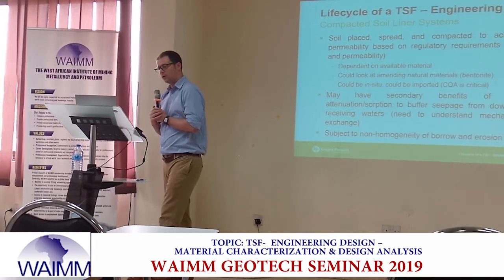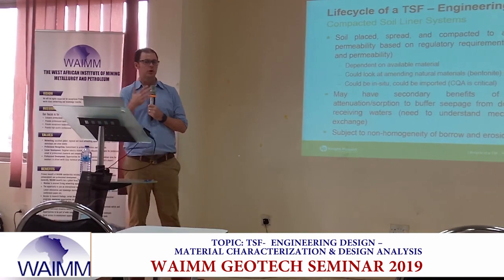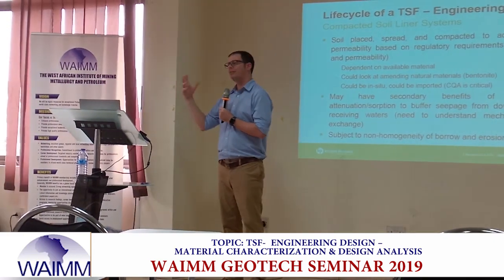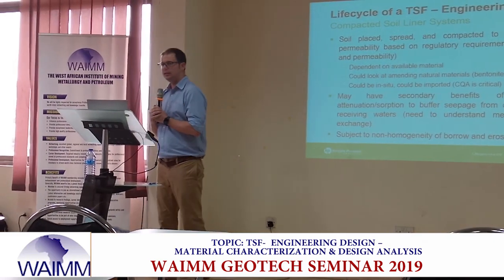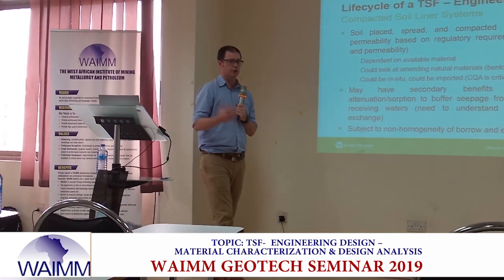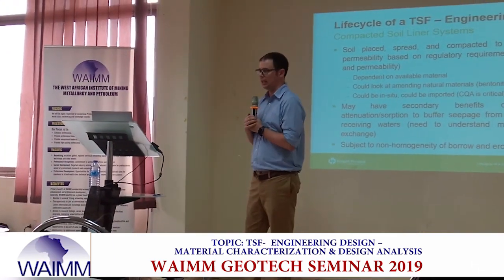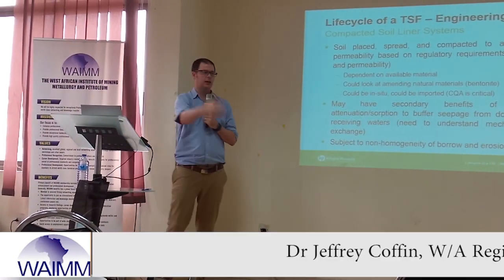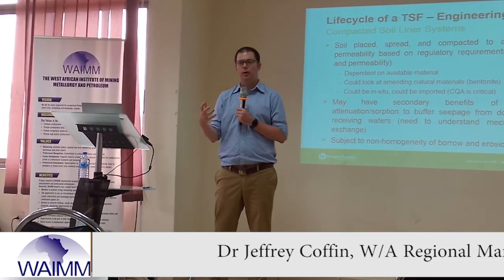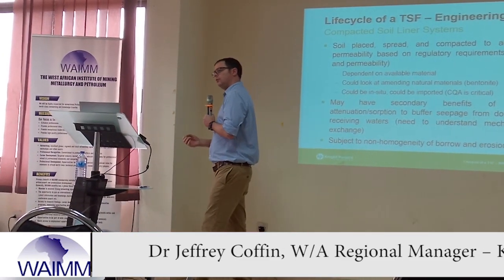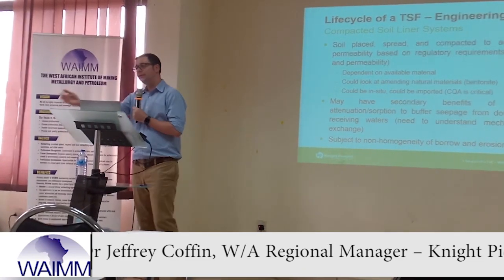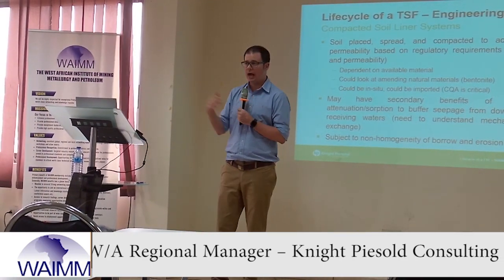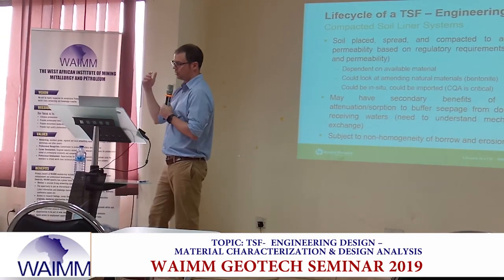When we talk about compacted soil liners, and I'm using compacted soil liner specifically because sometimes we talk about clay liners. Sometimes we want to have a clay liner. And in reality, very few places on Earth have pure clays available for use as clay liner. So if we start talking about, oh, a clay liner's required here, clay liner's required there, what happens if we get into a situation where we don't have a pure clay? For instance, a clayey sand may provide us just as low permeability as that pure clay. Okay, so that's why we're calling it compacted soil liner.